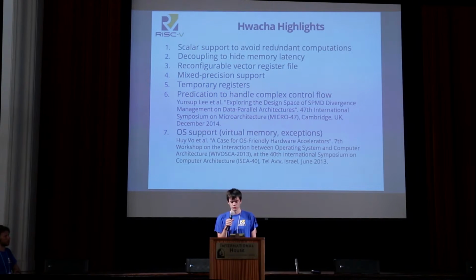We also have mixed precision support, which ties into that so that you can operate on smaller data types and pack them more densely and operate on them as widening ops or in smaller registers. In addition, we have this concept of temporary registers, which is kind of a new microarchitecture trick we have. It works well in scatter-gather cases and things like that to basically set up temporary values that aren't live across your whole function or your whole vector set of instructions. But you can talk more about that at the poster.